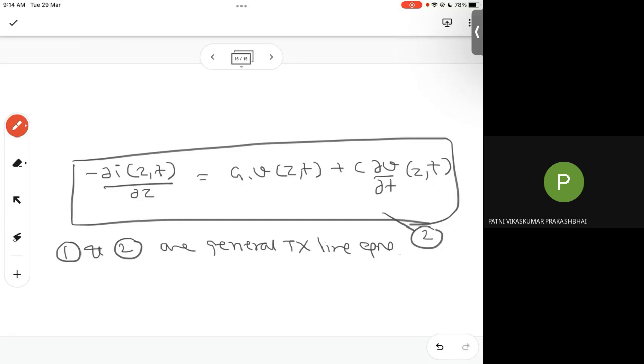A printed line is connecting them. So there also, how much length we should use matters, so that my system does not give undesired results. Even my printed line on a PCB could behave like an inductor or a capacitor, and the line joining the two components also has to follow these principles, which we are going to discuss.